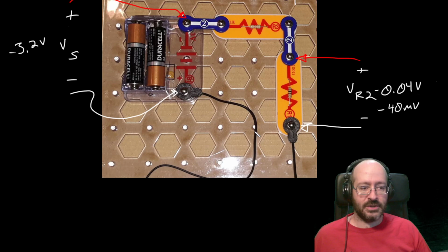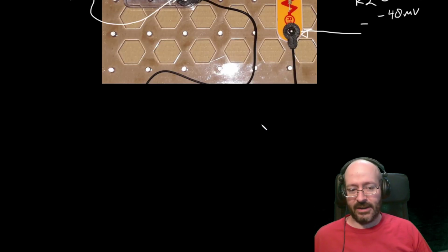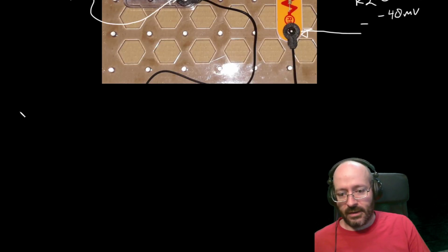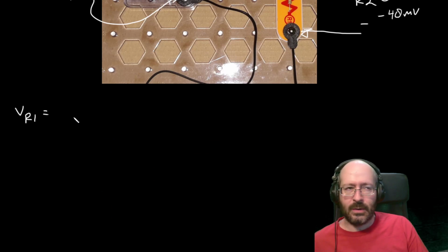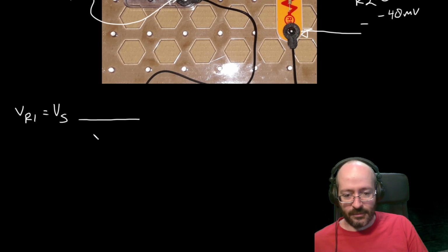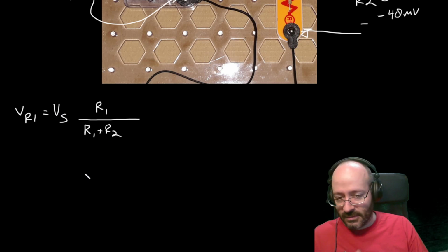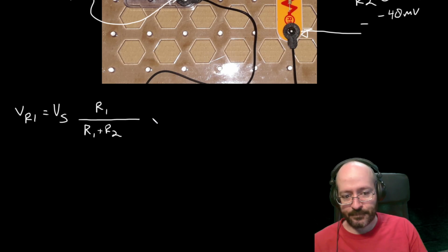And I'm going to write the equations the way that we typically write a voltage divider. Okay, so we were saying VR1 was equal to the current. Well, what was the current? The current was the voltage supply divided by, and I'm going to write that over here for a reason, the two resistances added together because they were in series. Then we took that current and multiplied it by the resistance we were interested in. So we usually write the voltage divider that way.